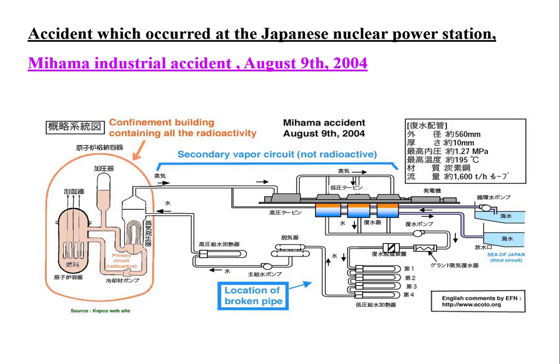They claim that they were not informed and not asked to do ultrasonic inspection because it is not mentioned in the maintenance procedures, details and requirements. So they claim they applied visual inspection to the exterior of the pipeline, and of course that external visual inspection will not reveal the thinning which could happen inside the pipe.